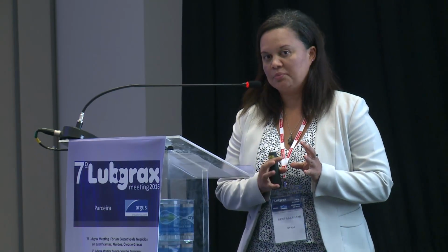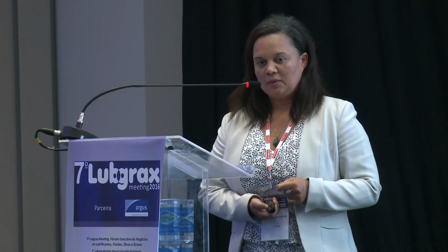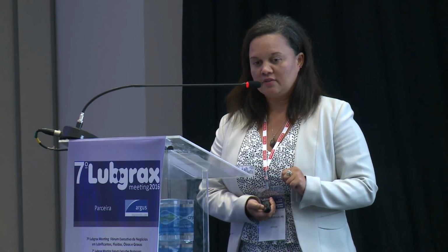So I think the interesting thing here is that the naphthenic molecules are actually acting as a natural pour point depressant when mixed with certain Group 2 or Group 3 molecules. It could be because they are cyclical in structure, so they could be preventing the crystallization of the wax-like molecules and delaying that process. That was interesting, and we'll touch back on this when we get into the greases. So those are the two of similar viscosities.